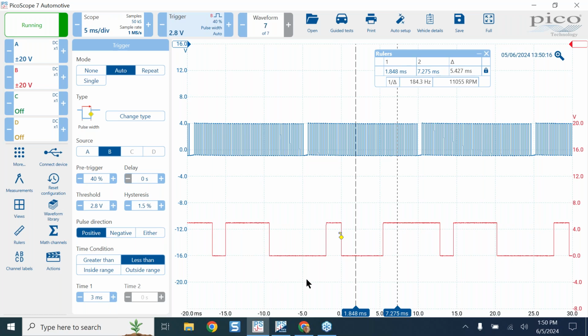Maybe not with simple edge triggers, of course, but when I'm using my advanced pulse width triggers, I just make sure that I have measured this properly. I just don't want to get lucky and randomly push buttons until the thing settles down, as some will do. You can measure it, make a proper selection here, and stabilize the pattern faster than you can push buttons and get lucky. That's what I've always found. So if I can take one measurement, in this case I took 2 because I did the wide one, and then we wanted to do the narrow one, and then you can do in between if you wanted to do the medium.